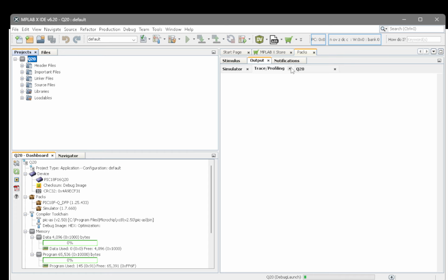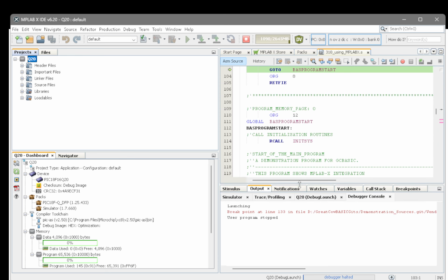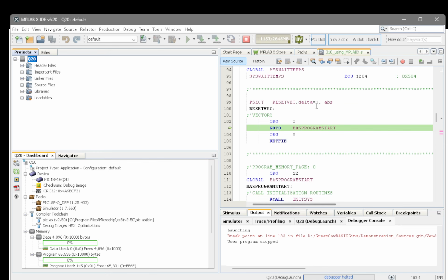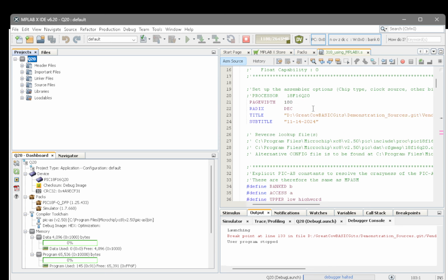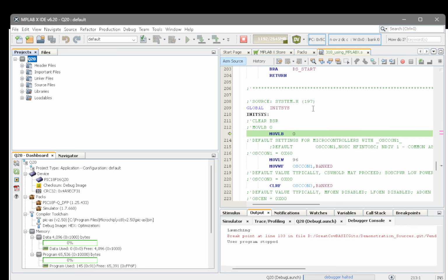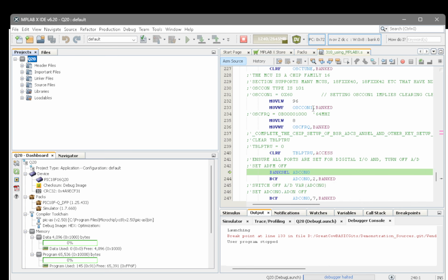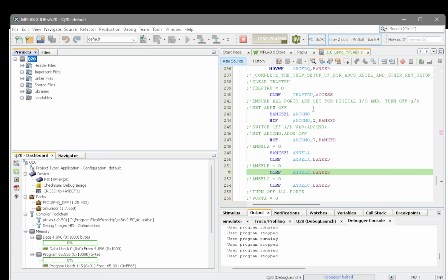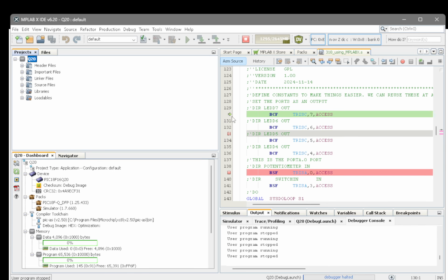It's now launching the MPLAB debugger in here. Here we go, look. And here is our source program in the debugger, look. You may say it's not the same. I'll prove it is in a minute. So I can press function key F7 and I'm walking my program line by line. It's walking through the initialization of the chip. And then here, if you look in here, here is our code.